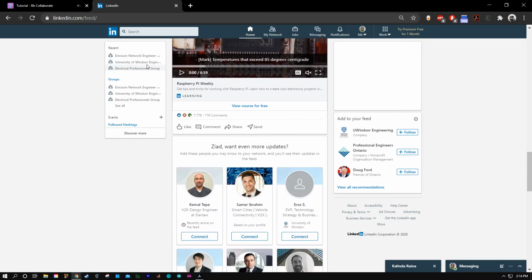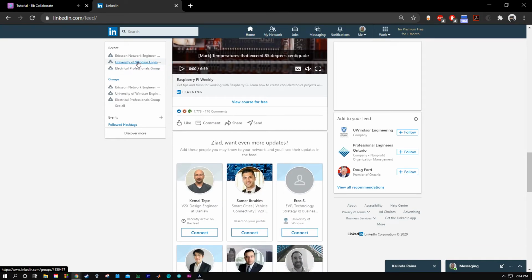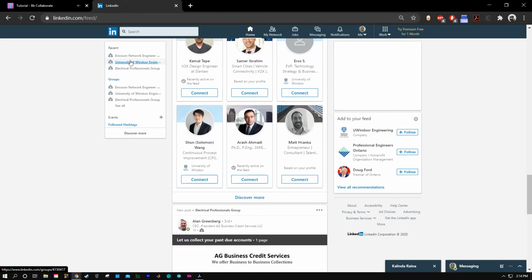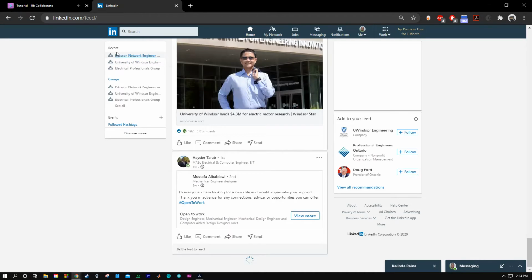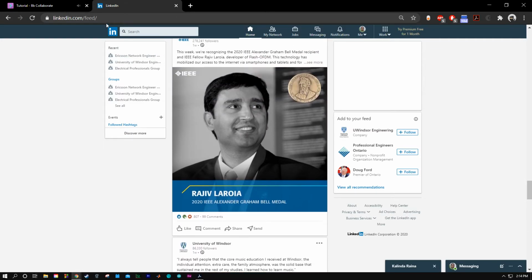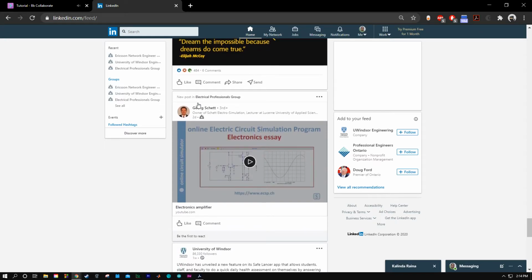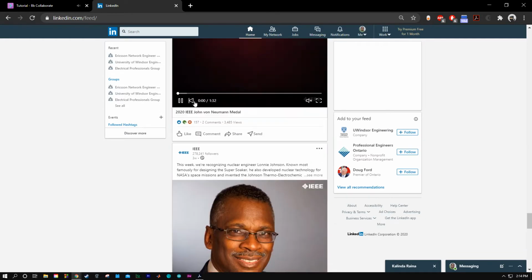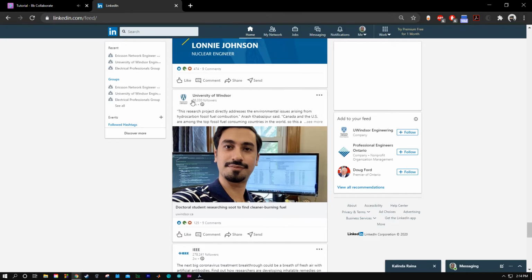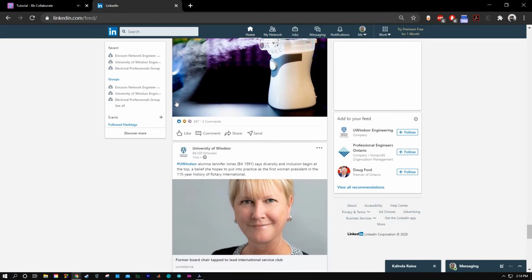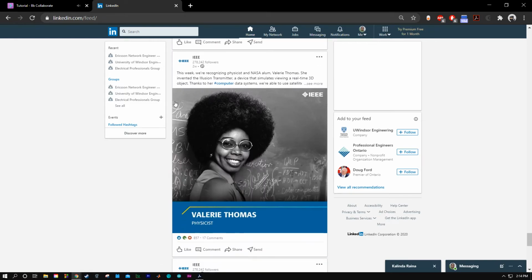When I do the KVL in this direction, going that way, I see that we've defined current going this way for both of them. When I go this way, I'm going against the current in my rotation. And I'm going with the current at this part of the loop. So this drop here is V1 across this resistor. That's negative because it's going in the opposite direction of the current that we had defined.